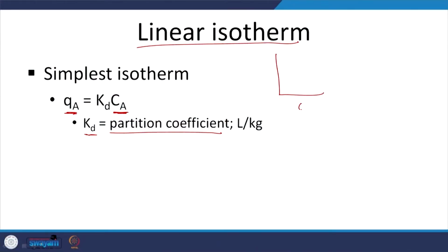Why is that? Because your media has, at the end of the day, certain properties, a certain limited surface area. So it's not as if you keep increasing the concentration and Q is also going to keep increasing. If this is C and Q, fine, this is reasonable, but it's never going to be like this, because there you have thresholds. So this is rarely used.